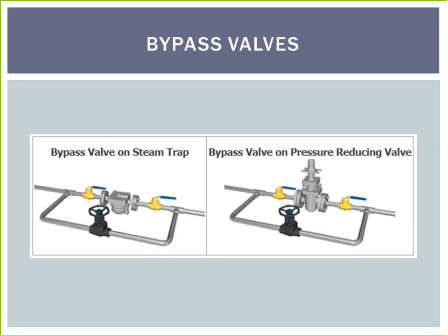Bypass piping can roughly be divided into two categories. Bypass piping that acts as a backup line to allow operation to continue while damaged equipment such as pressure reducing valves and steam traps are isolated and shut down during replacement or repair, or bypass piping whose purpose is to supplement the performance of pressure reducing valves and traps. These different objectives require valves with different features. Therefore, the optimal valve models will be different.